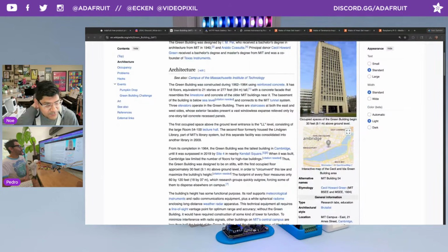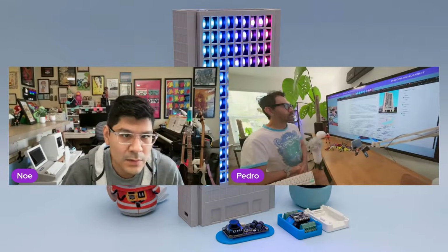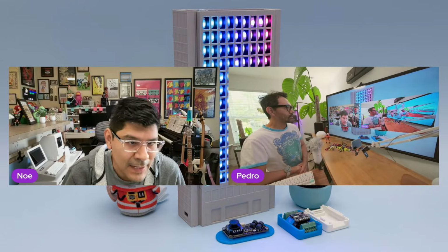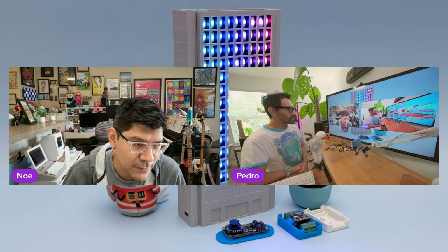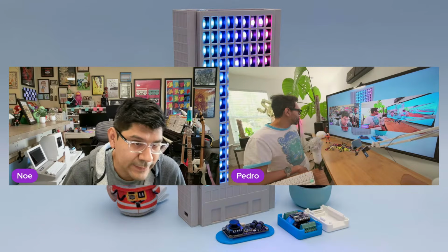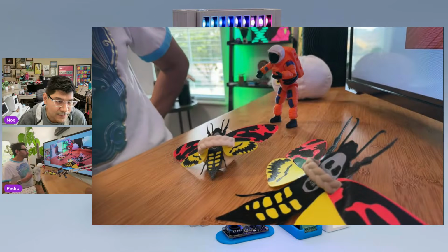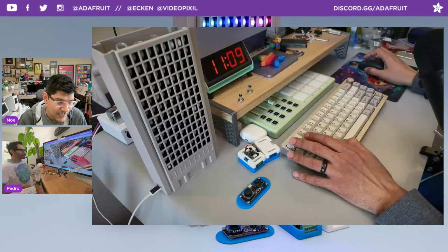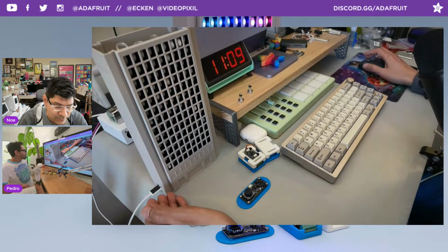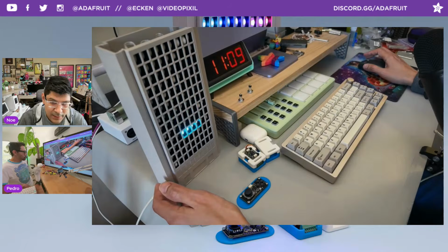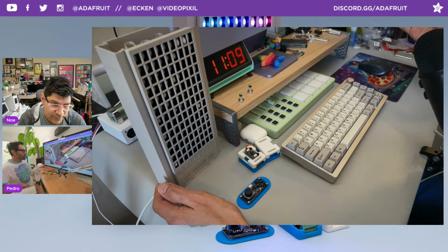I'm not too concerned about having exactly 1-to-1 because, again, I have to limit the size to the bed volume of my 3D printer. What 3D printer? It's the X1C from Bambu Lab. I am just clicking everywhere. But yeah, it maxes out at like 250. It says it can do 256, but you actually can't because you have to have a little bit of extra for the Z-hop.